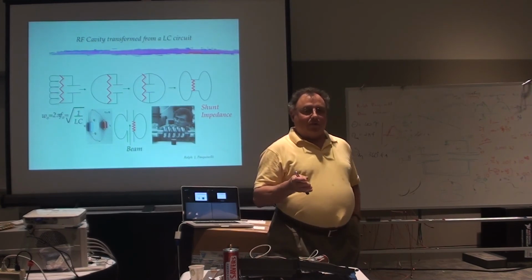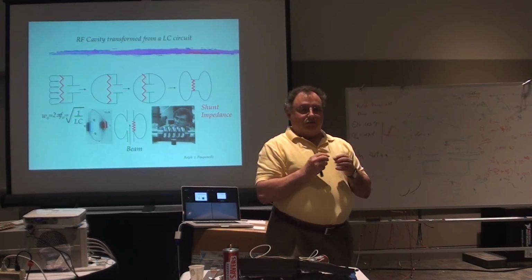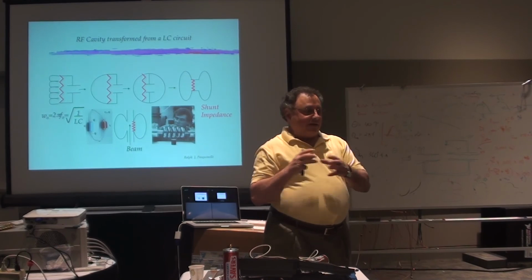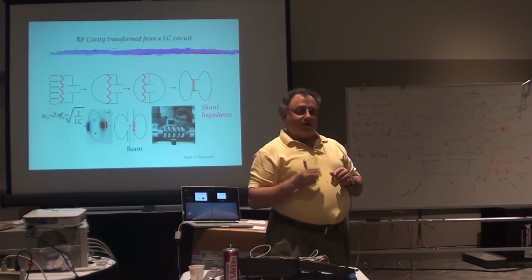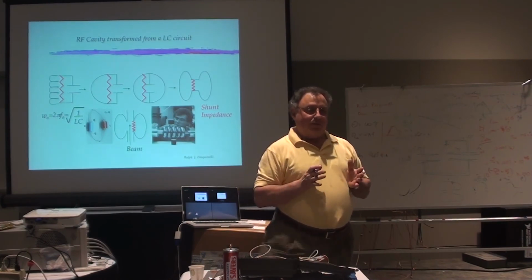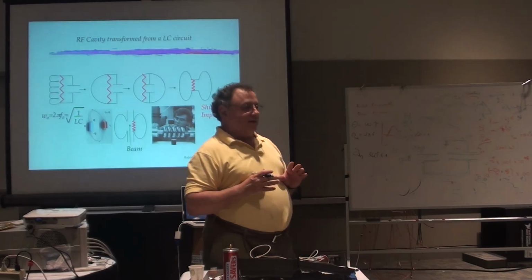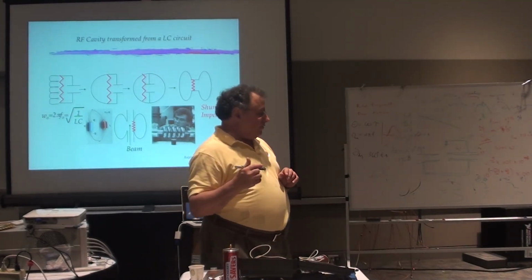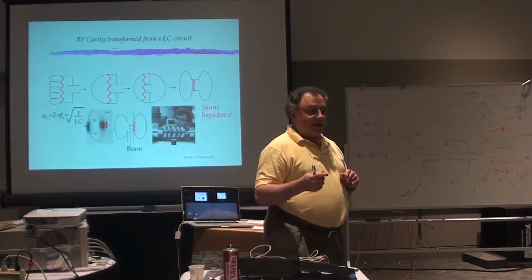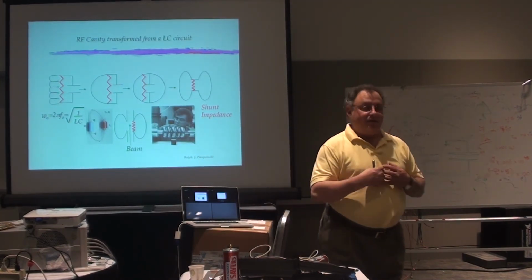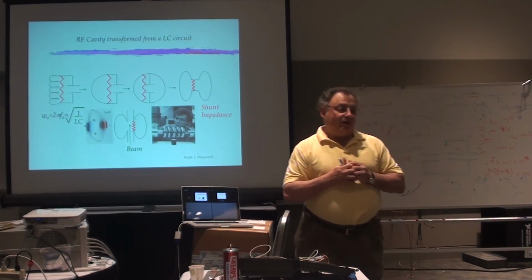It's made out of aluminum, but the two clamshell halves are just held together. There are pins to align it, and there's that band clamp to just hold it together. If that was brazed together, as a real cavity would be, made out of aluminum, that might jump up from 600 to 10,000. The real ones that we have at Fermilab look just like this, and they're made out of very high quality copper, and they're brazed and degassed, etc. Those have Qs of about 20,000.